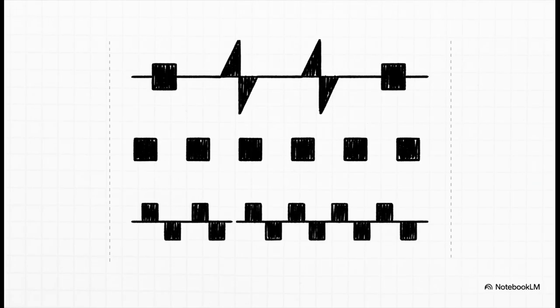And it's not just the most significant bit. Nope. Every single bit in that digital word is telling the same story. These patterns might look more complicated, but they all share one key characteristic. They are all just nonlinear versions of the original signal, and they repeat with the exact same period. What does that mean? It means they are all contributing energy only at the harmonic frequencies of that original signal.